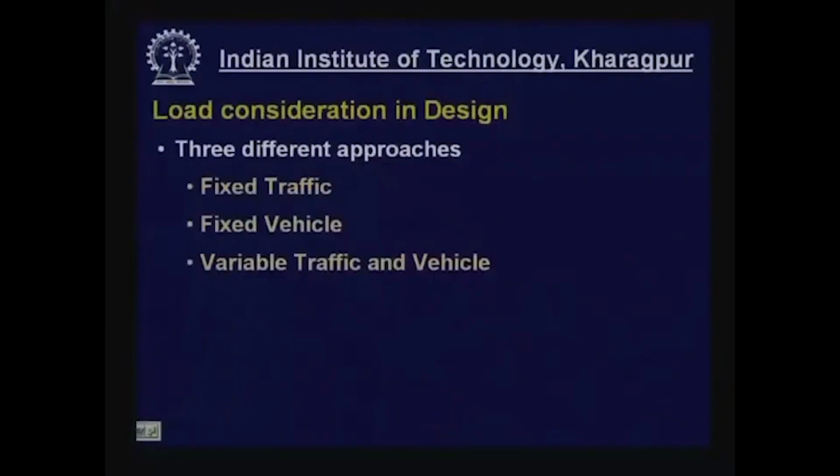Load consideration in pavement design is usually adopted as per three different approaches. The first one is the fixed traffic approach, then we have the fixed vehicle approach, and the third approach is the variable traffic, variable vehicle approach. Let us take up each one of these approaches one by one and discuss them.